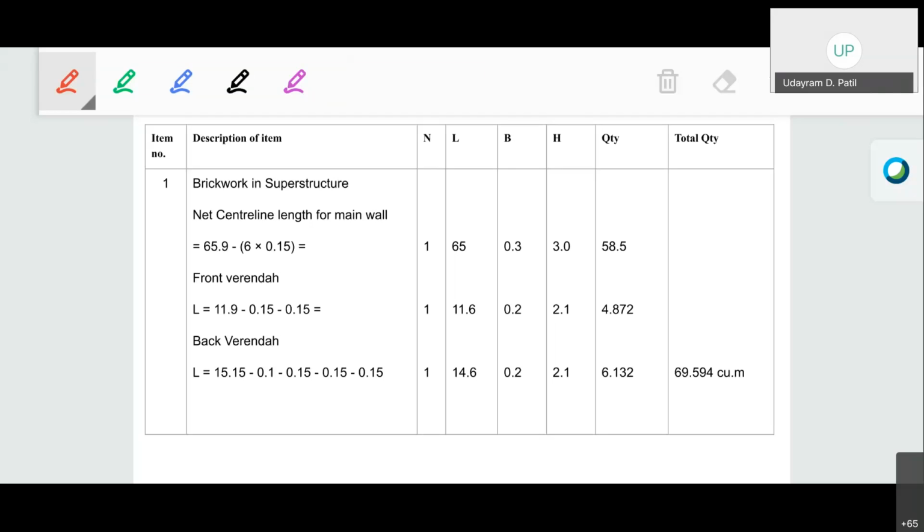Okay, a small calculation mistake in the center line and that will affect the whole particular estimate. Whereas in case of the long wall short wall method, if there is a calculation mistake in a certain long wall, that will affect only that particular quantity. Therefore, if you are more confident about the center line method, go with it.